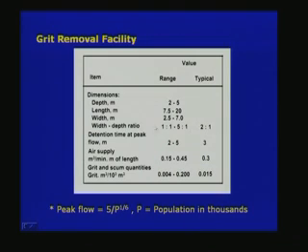So, I have the length, and the detention time at peak flow is 2 to 5 minutes. The detention time is the time for which the flow stays in the aerated grit chamber. That is at the peak flow, not at the average flow, maximum flow, so 2 to 5 minutes it will remain in the